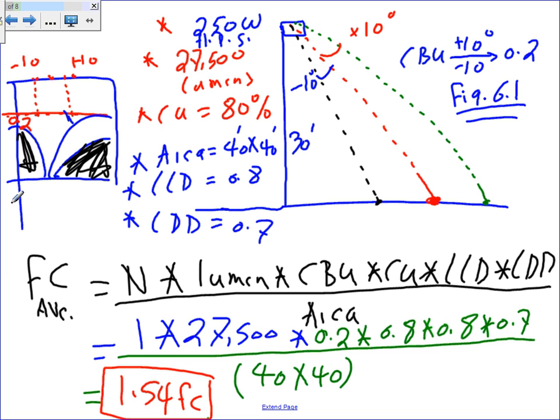So if you can see, guys, thank you, Chris. This graphic is all based on the height of every fixture. Based on its height, the beam utilization will be different. The luminous distribution will be different. So you'd need data from various components, or a factor that takes it into account. Most of the time, they give you: if you mount it at this height, you have to multiply by this factor.